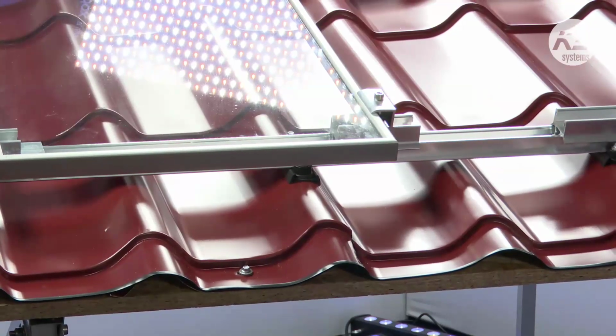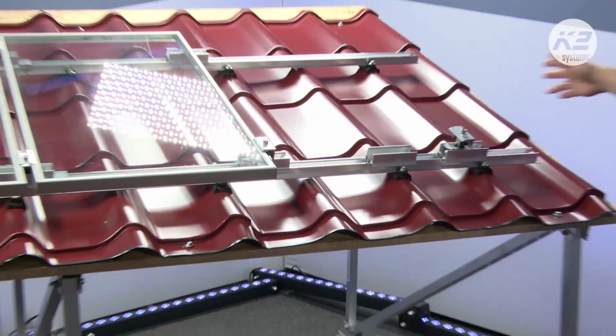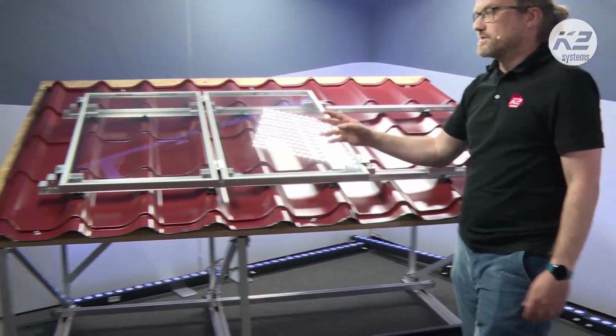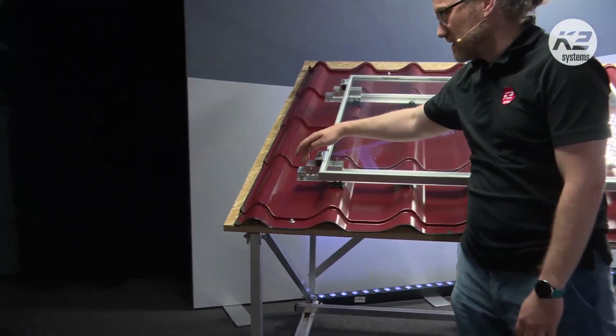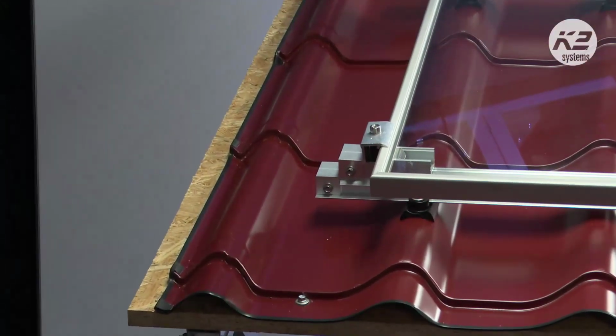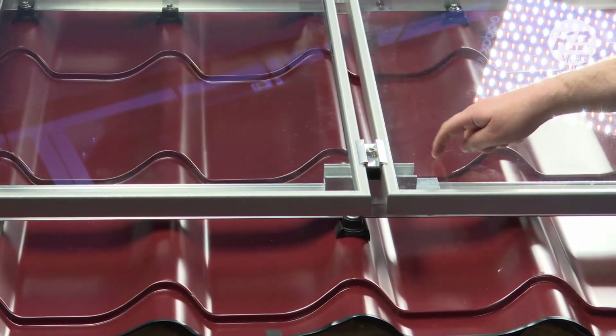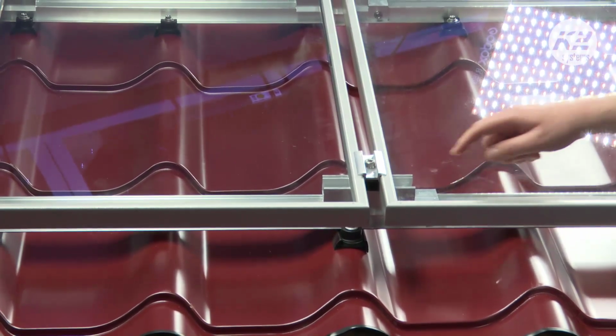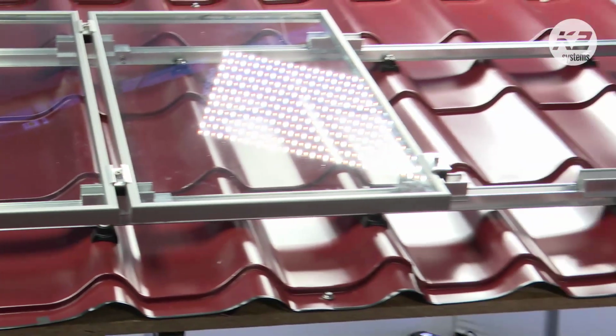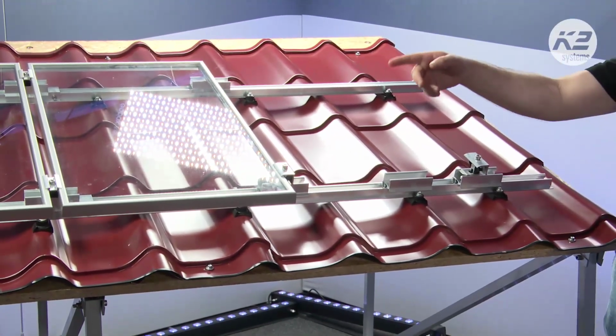So maybe the question which comes several times is about our anti-slip clip. How many do we need? How many do we have to install? So Klaus, maybe let us show once again. You need per one long rail, even if it's connected with another one, yeah, even if it's a longer rail with two rails, you need only 3 anti-slip clips. It's always installed like here, 2 on one side, and a third one here in the middle. So always 3 anti-slip clips per rail. You don't need to put additional anti-slip clips here on the other side. Yeah, it's only there.